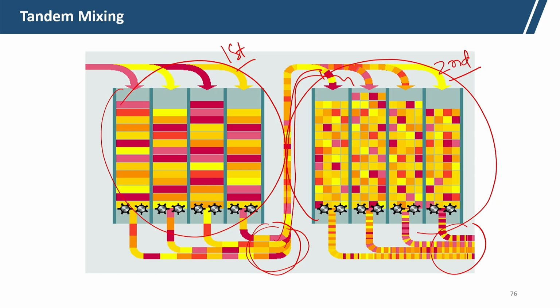So, at the blow room stage, at the mixing line, we get a higher opportunity to get homogeneous blending. But the main problem with this type of system is that you need a larger space, the capital investment will be more, and it may sometimes damage the fiber due to repeated opening and repeated action on the fibers, but it results in very homogeneous mixing.